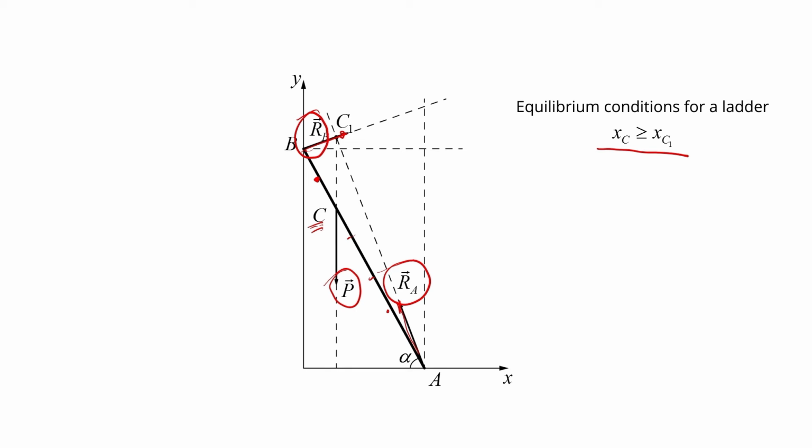Why is it disturbed? And at what point, B or A? Let us draw the force P in this position. Assume that we have the undisturbed equilibrium condition in the point B, and that RB is still directed along the cone generator. Then, according to the three-force theorem, we claim that RA, RB, and P should intersect in one point, in this one.